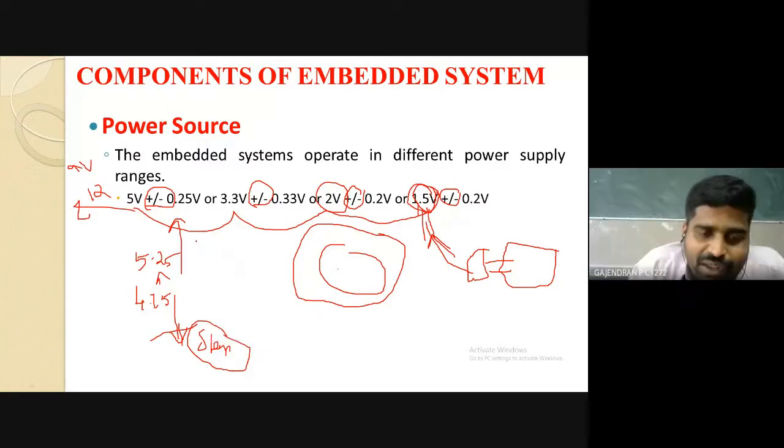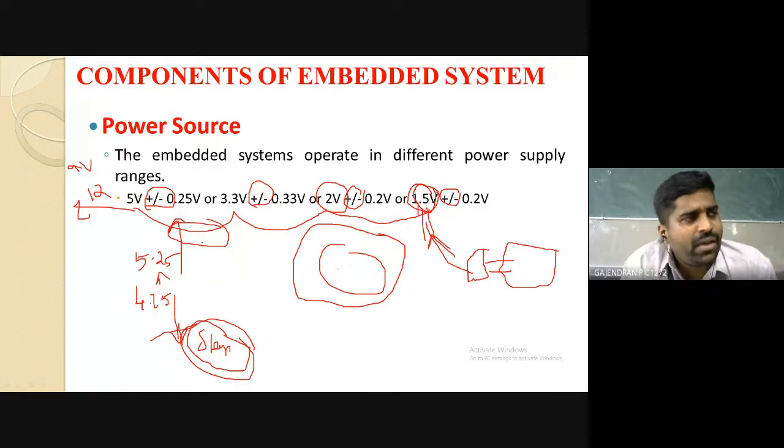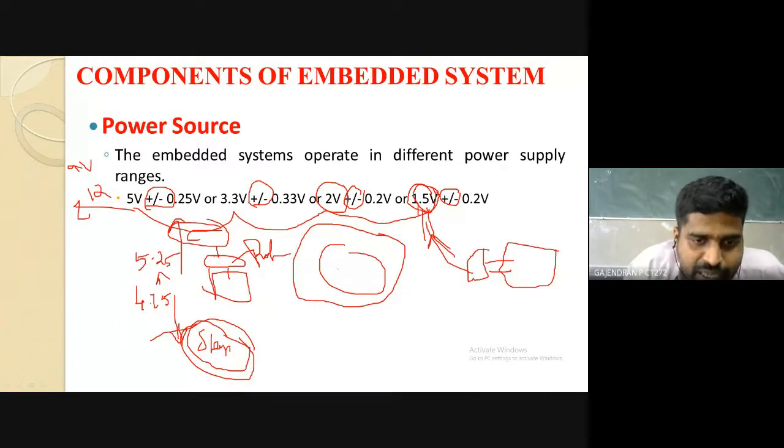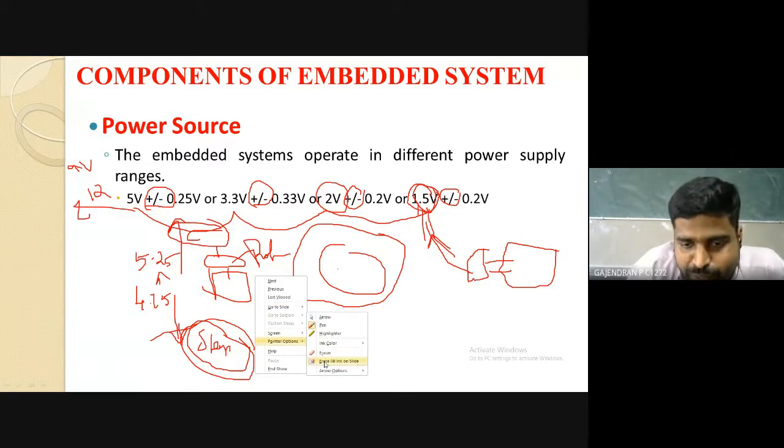Saturation. Saturation, okay. What will happen to your real hardware? It will become damaged, am I correct? It will become damaged, but it won't. Can you tell me what may be the additional one here? Here sleep or shutdown; here what may be the additional one? We may have it between your chip and power. You have some kind of protection circuits: surge protection, high voltage protection, under voltage, over voltage. Those are all taken care of by specific hardware circuits. Thereby you need not worry about this.